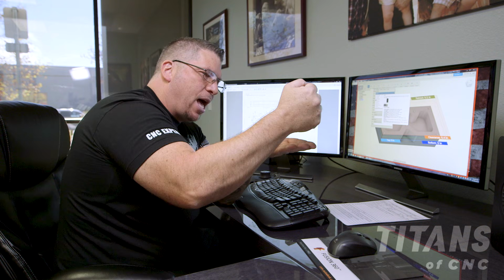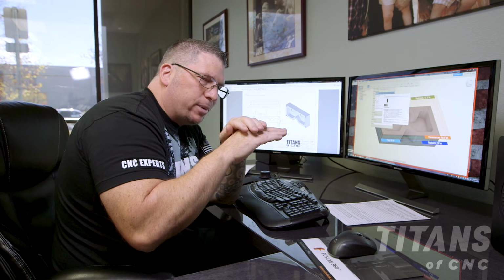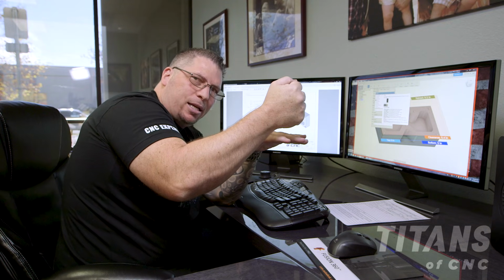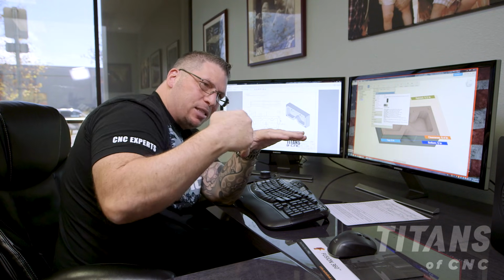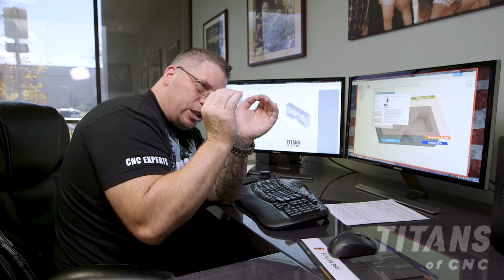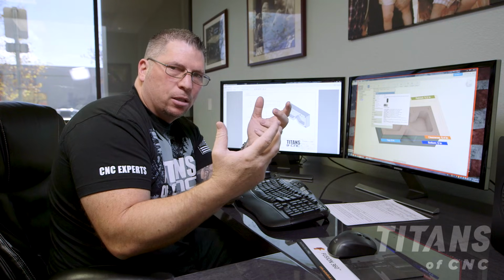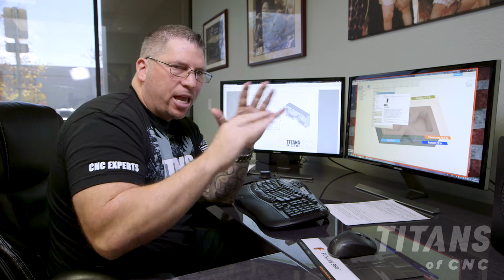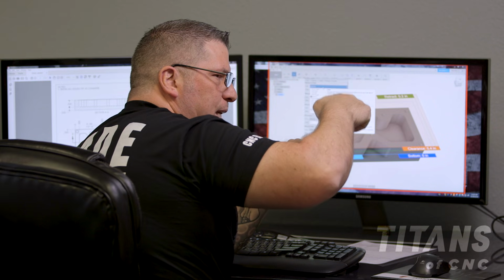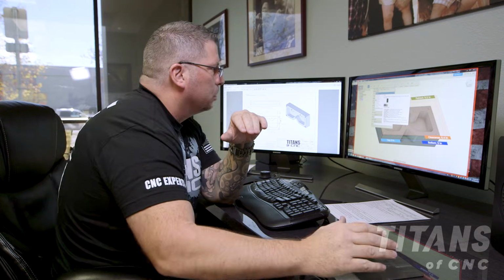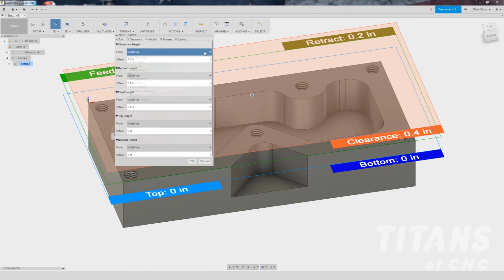Then when the tool's at a half an inch, I can say, this is where my Z surface, the top of the part is. The tool looks like it's at a half an inch above. It's an absolute position that I can really look at and say, yes, that's good. It's not going to crash. It all makes sense to me. Basically, what I like to do is go model top on everything so that wherever the Z is at any given time, I can see how it relates to that top surface. So the first clearance height, going to model top.